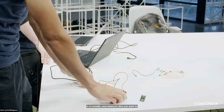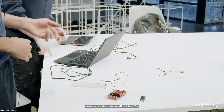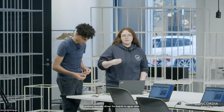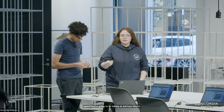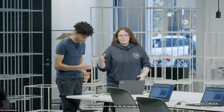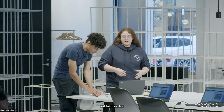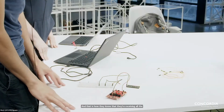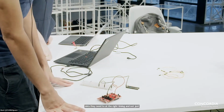The protocol basically allows the boards to agree on what speed they're going to be talking at and how they're going to be receiving data. So they're going to receive a byte that'll tell them the message is starting, and then they'll receive something at the end that says the message is over. And that is how they know that they're receiving all the data they need at the right timing and not just random data. Yes, and right here, as I said, every component must be grounded.